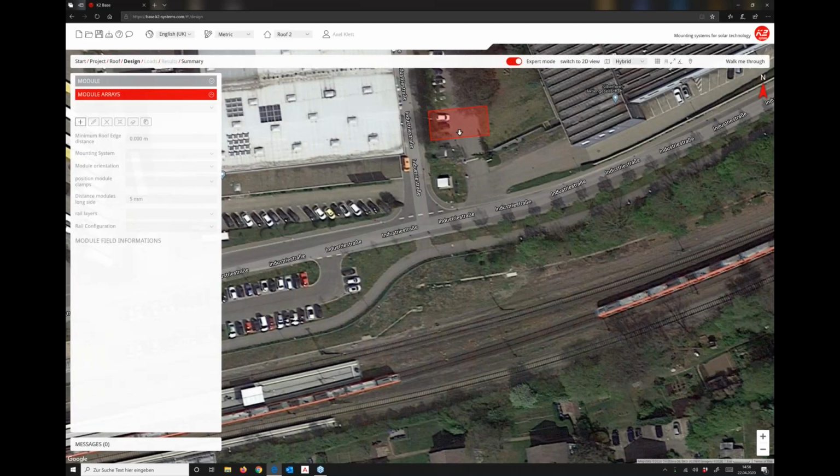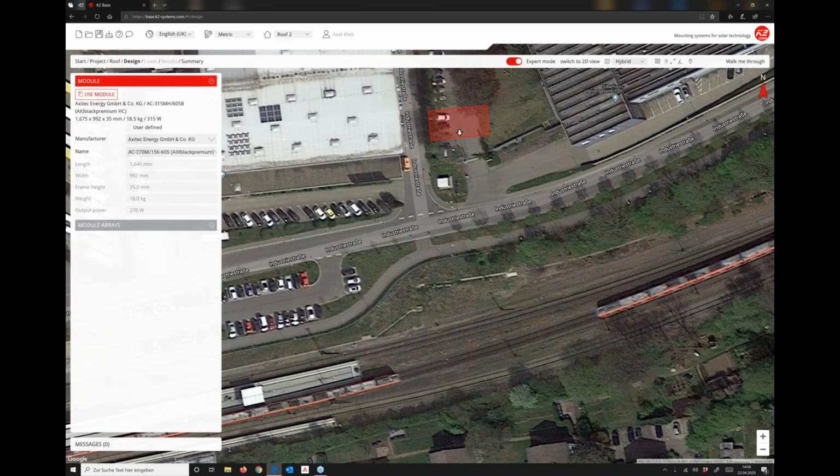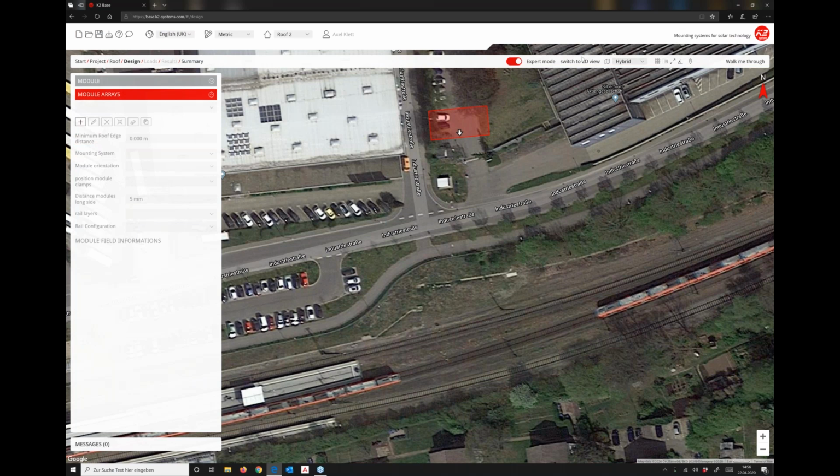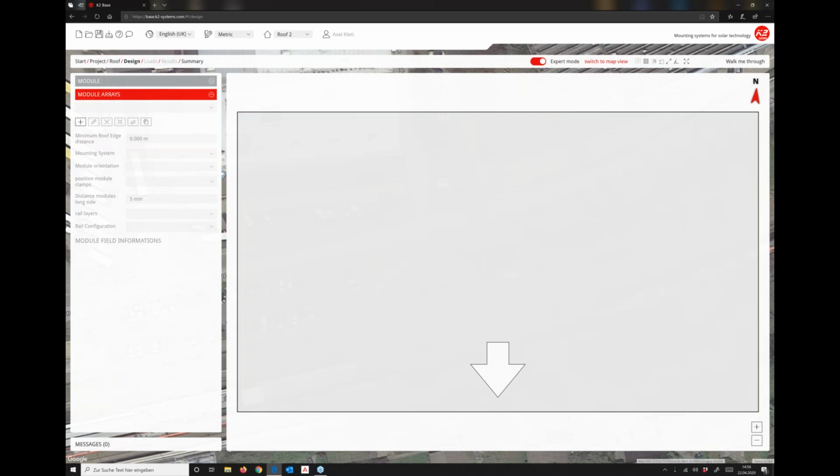Using the same model, if you have more than one roof, you can select the model you use on the first roof. I say, okay, we use it, so we don't have to look for it. And here I switch into the 2D view and go to the little pictogram on the side and show the under construction. And so you can show the rafter.